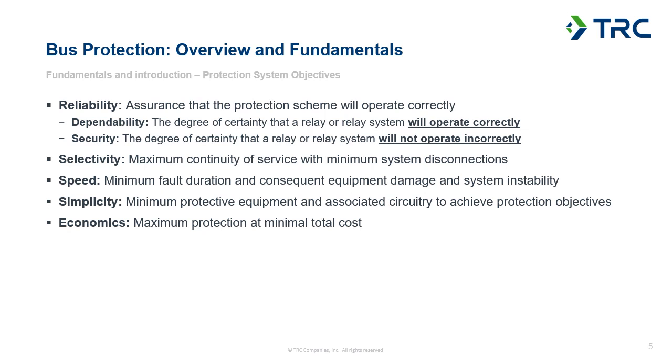And then finally, economics. Generally, buses being a critical component, we're seeing more and more utilities, even at lower voltages, justify some more advanced bus protection methods, based on the importance of all these other factors outweighing the economics of having to buy additional relaying and things like that for them. So we'll touch back on these in each of the schemes we'll be describing throughout the remainder of the presentation today.